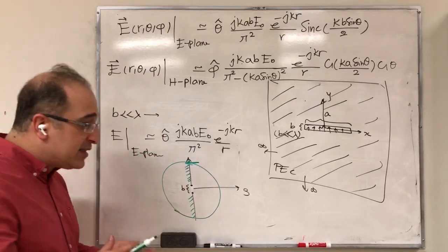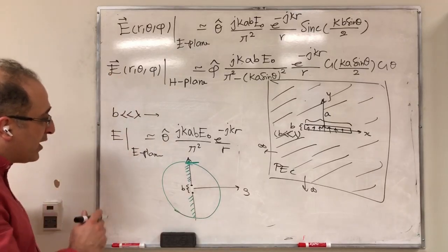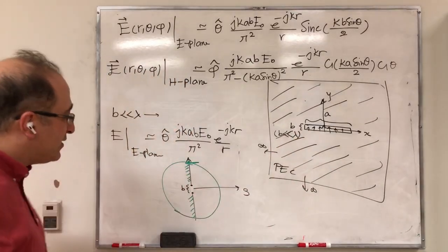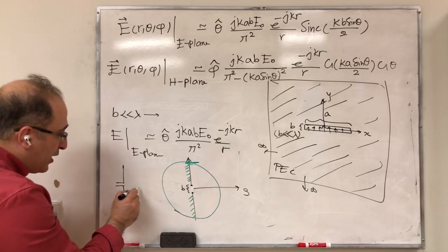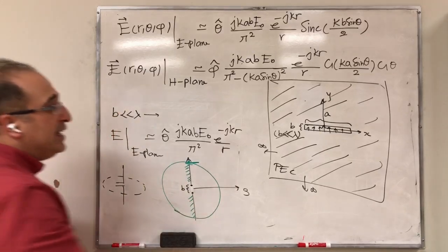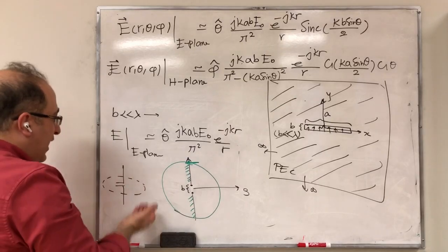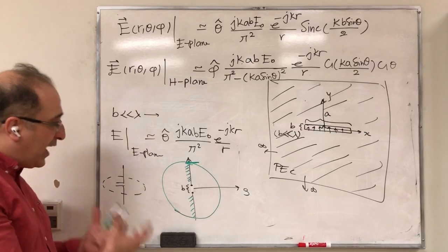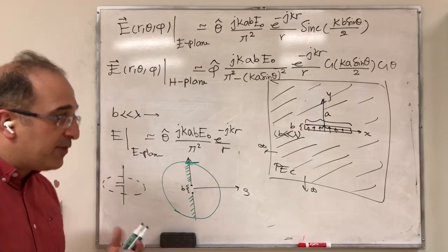Now, remember the Babinet principle and the extension by Booker, that we said this is the complementary antenna to the dipole antenna. Now, if you go to the dipole antenna, you know that for the dipole antenna, the H plane is like this. This is now the E plane. You see, the E plane of this has this omnidirectional characteristic, but the H plane of the dipole had this omnidirectional characteristic. So that somehow shows their relation, but there are differences too.